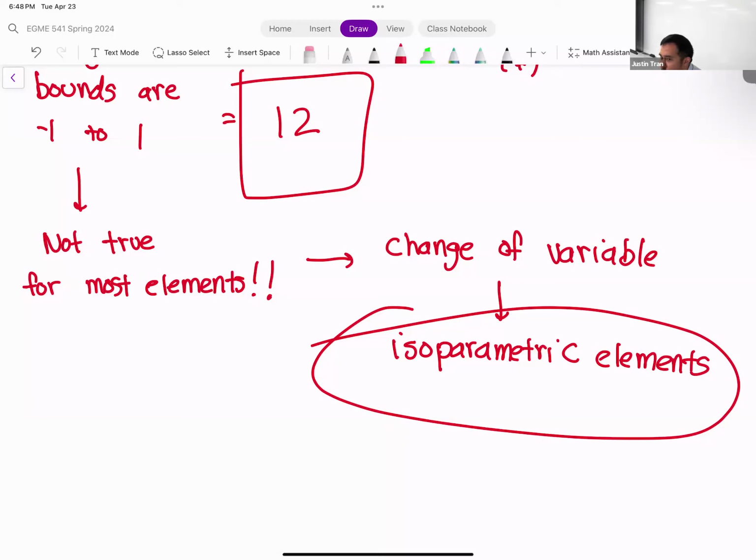I think we just simply use the midpoint rule. So you would evaluate the heat source term at the middle of your finite volume cell, and then multiply it by any grid spacing or time step size, just to keep it consistent with the rest of the equation. Does that make sense?